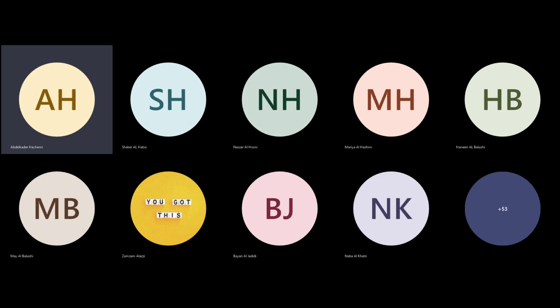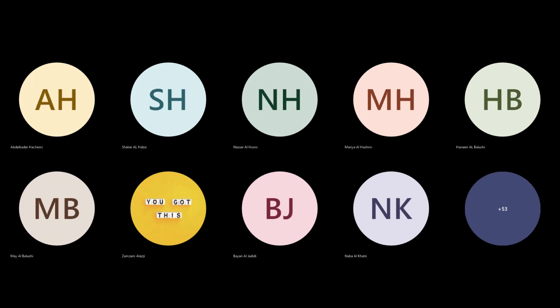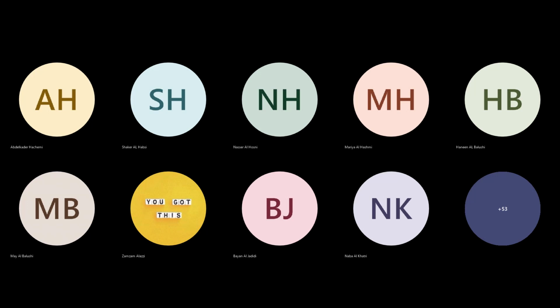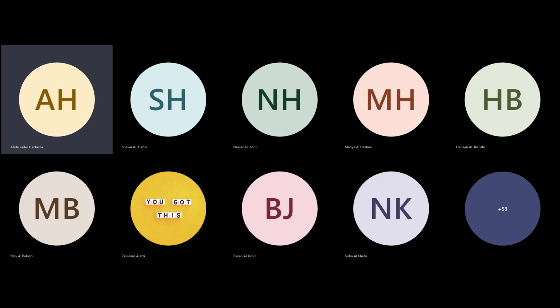That means if we look at the e phi direction, for the velocity v we have R phi dot. This is the circumferential one. And for the acceleration, we have the two terms here, 2 R dot phi dot plus R phi dot dot. This is in circumferential direction.